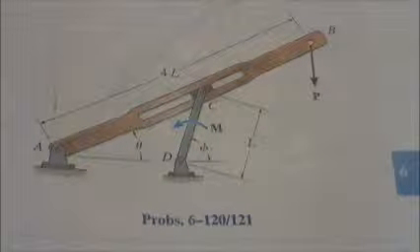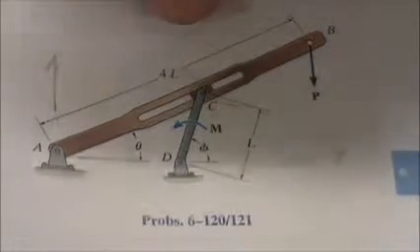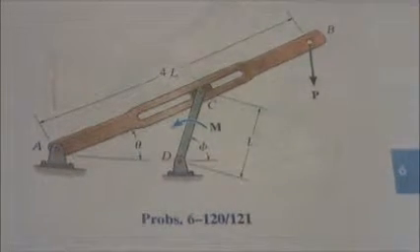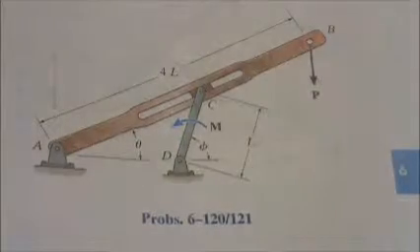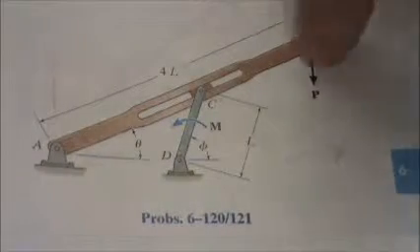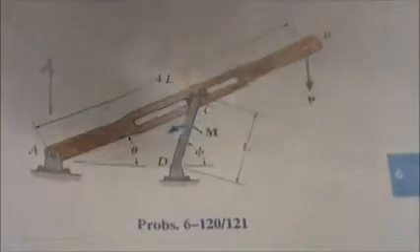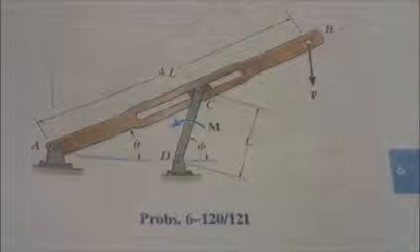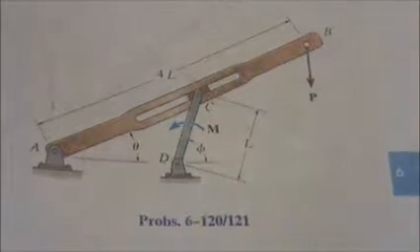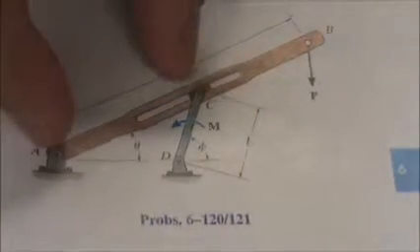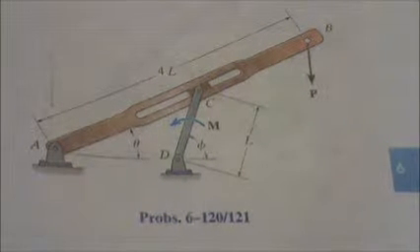So there are a couple of things that we need to watch out for in this problem. First one being the block at point C. Since it is confined within the channel, it has a normal force that acts on each bar, and that can only be directed perpendicular to the line AB. The second one is, if we are going to relate the normal force between the bar AB and CD, we're going to have to find this length x between A and C, so that we can find the length of that moment arm.